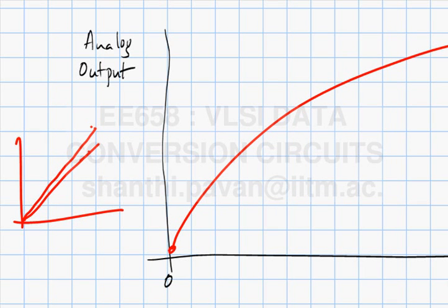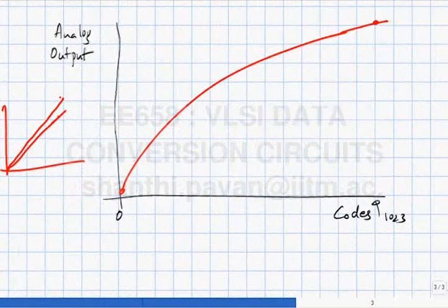And you can see that even though this lies on a perfectly straight line, if I compute the LSB size from this curve and this is what I thought my ideal was, I clearly see that even though the converter is perfectly fine, it would seem as if there is a large INL here. The INL is going on increasing from 0 to something very large and positive. So that's clearly not the converter's fault, it's just some gain error, and as we said, gain error is benign.